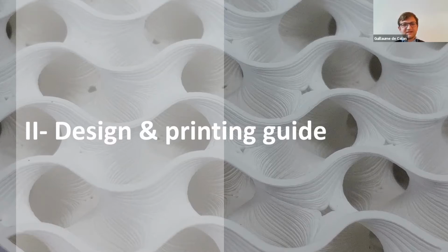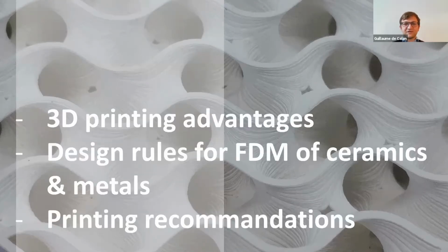There's three parts in this. The first one is talking about the advantage of this technology. And this advantage should be, as much as possible, included in your designs. You should take profit of the advantages. Then there's a few design rules for FDM of ceramics and metal, and we'll go through them together.